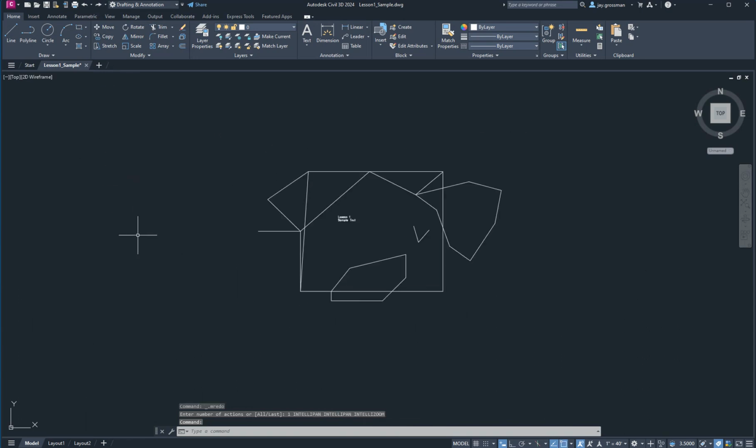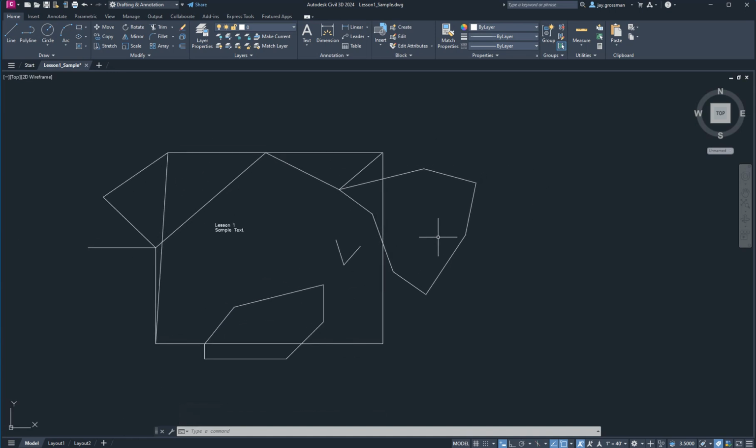So there's that. If things don't look right, like if you draw a circle, sometimes they look chunky, you type in regen and that will redraw your entire drawing. Kind of reloads it or redraws it and refreshes everything. Sometimes you delete pieces and there's little chunks left. You hit regen, that'll fix that. So you'll probably use regen quite a bit.